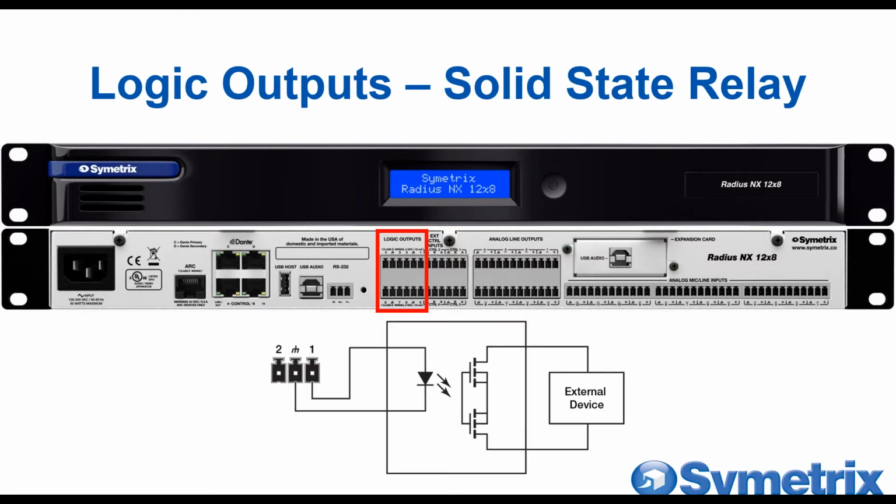Another good option for relays is a solid state relay. Those have an internal LED instead of a coil, so they have way lower turn on requirements. Again, look at the specs, but there are plenty out there that could be driven directly off the logic output.